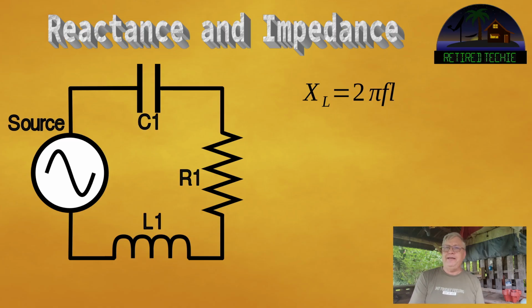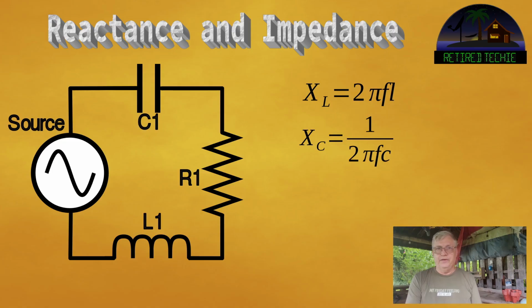There's some interesting applications for this, which again, different video, but I just wanted to mention it. We also have a capacitor, and you'll notice capacitor is kind of opposite of the inductor or coil. It's measured in farads. And in this case, to get reactance, it's X sub C equals 1 over 2 pi F C. So like I say, it's sort of the inversion of inductive reactance is capacitive reactance, so to speak.